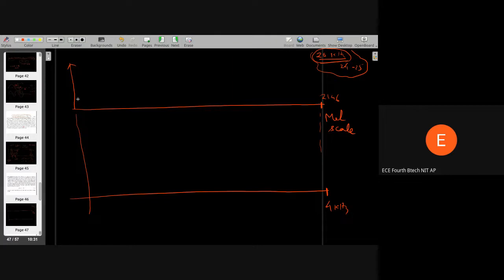So the process is, this is what we do. We'll divide this MEL scale into equal portions, equal bands, and the number of bands is generally around 20, or 20 to 24. This is the number of bands we take. This is what we have found to be useful in signal processing, based on the concepts of critical bands and all that. So in the MEL scale, not in the analog scale, we divide in terms of equal bands.